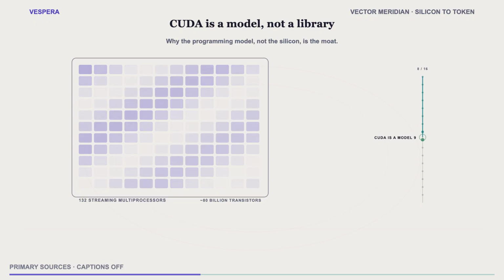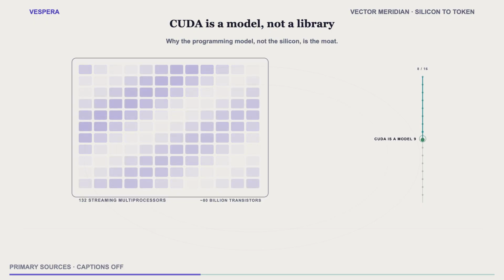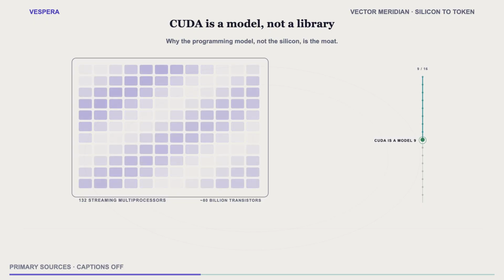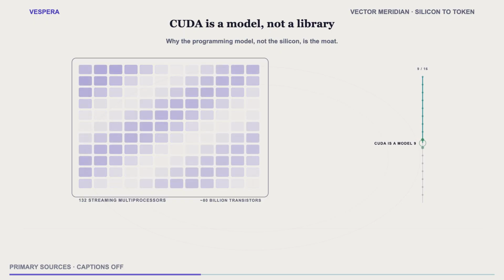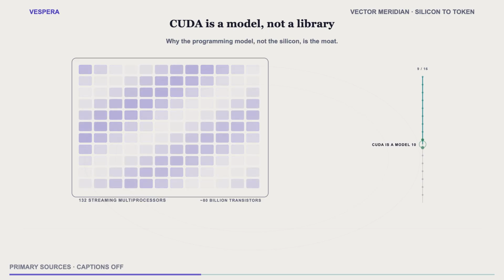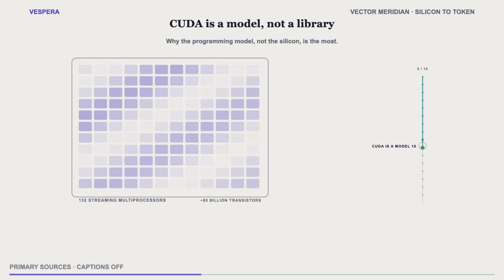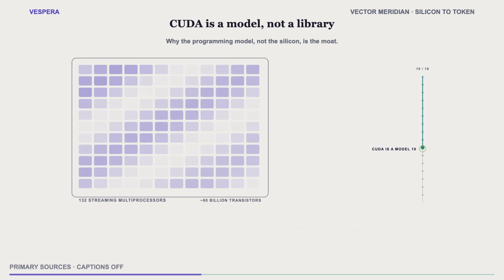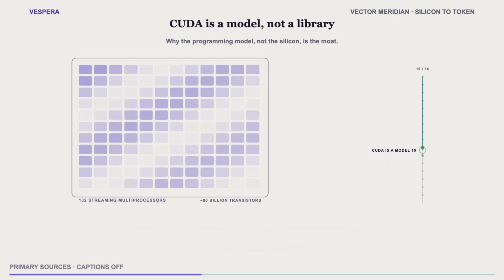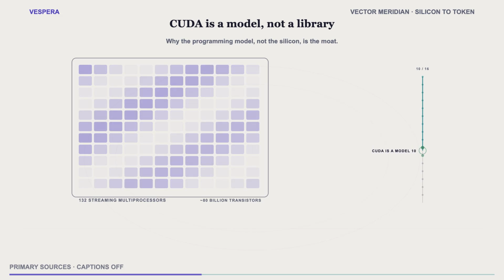So Act 2 closes with a machine that has committed hard in a particular direction: 32-wide execution because control logic is expensive, thousands of resident threads because memory is slow and concurrency is the only cure. Fixed function matrix units because they are 30 times faster and generality was too expensive to keep. And a programming model that has been etched into the professional habits of an industry as thoroughly as the matrix units are etched into the silicon.